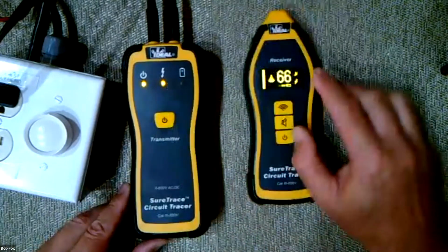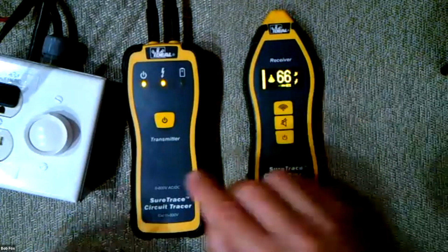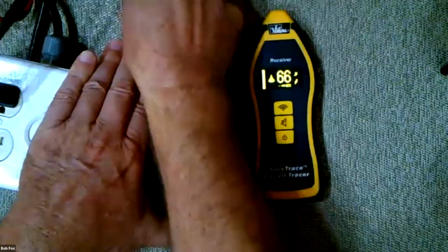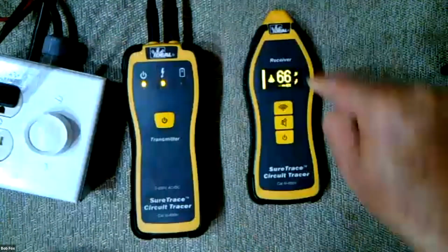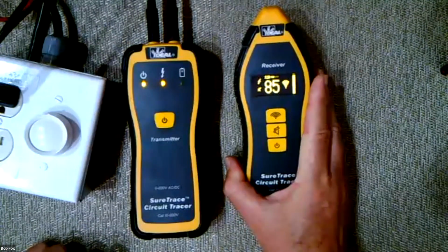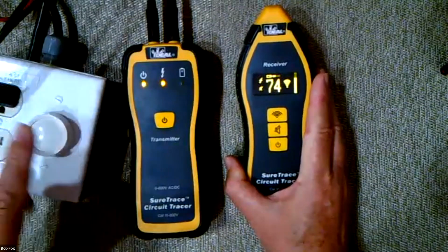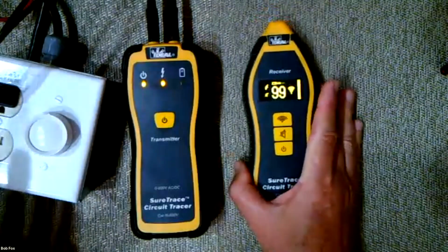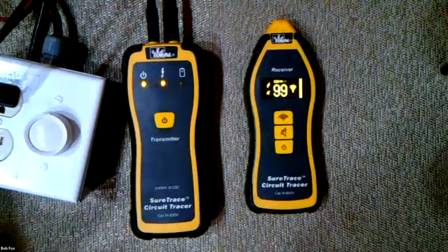And if you noticed, that's the lightning bolt that Chris was speaking about before. As soon as you unplug, that goes away. As soon as you plug it back in, that sends an additional signal that lights that up. And that allows you to confirm that you're broadcasting the signal onto the branch circuit that you're trying to identify. So again, when you shut the breaker off, that goes out, you know you shut off the right breaker.